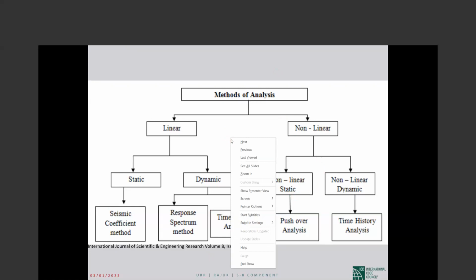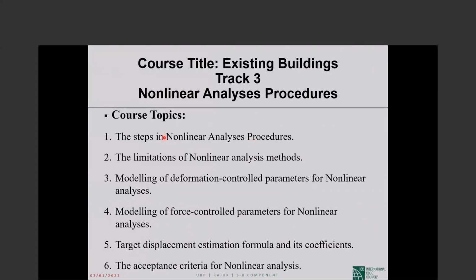Okay, so what we expect from tonight is to review the steps for the nonlinear analysis. There is not much limitation for using nonlinear analysis methods. Just if the higher mode effects are important, it's better to use dynamic, not static. And in different codes, there are checks that we can apply to see if the higher modes are